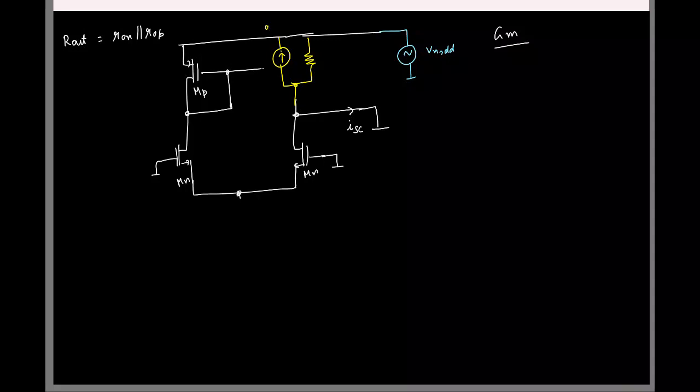Okay. So this current source is gm·vgs, and this is, say, r0 of the PMOS. So the short circuit current will have contributions from this current, and the current that comes here, right? Let's say this current. So what is the current flowing through the r0 of the transistor? What is this current? VDD by r0. Right?